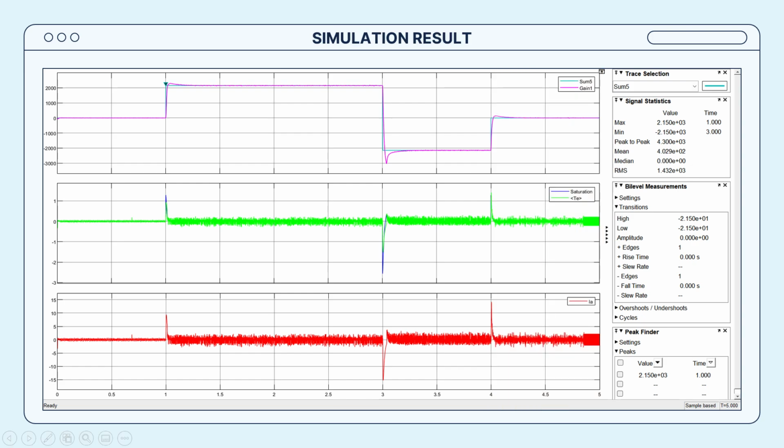The 4-quadrant operation confirms the capability of the permanent magnet DC motor in delivering satisfactory performance in motoring and braking modes, both in forward and reverse direction. The ripple in the graph can be related to the proportional gain Kp and integral gain Ki parameters of the PI controller used in the control system. As the value of Kp increases, the system becomes more sensitive to change. This can result in faster response but with the drawback of overshooting and oscillating, which can contribute to ripple.